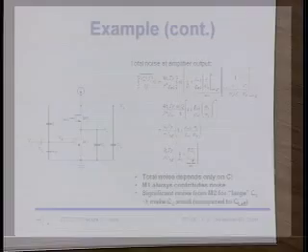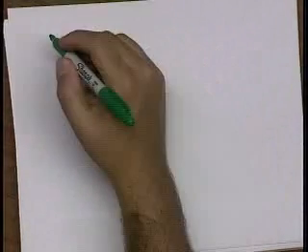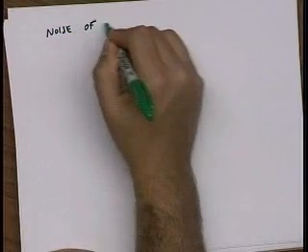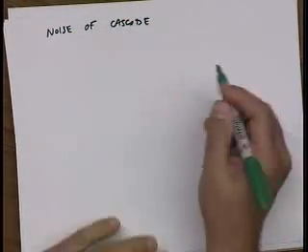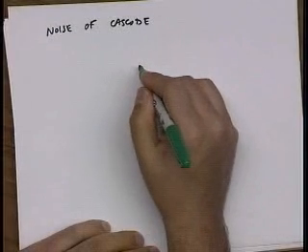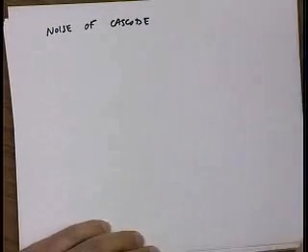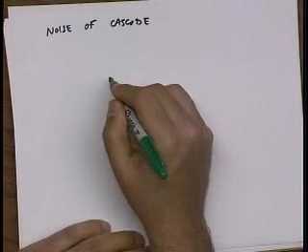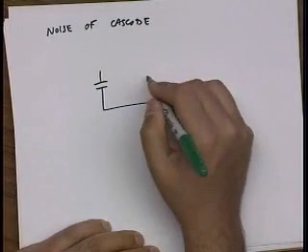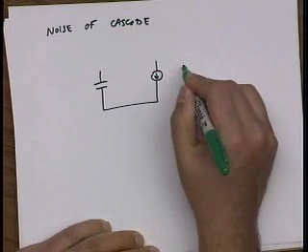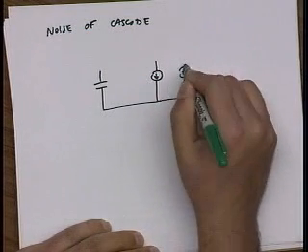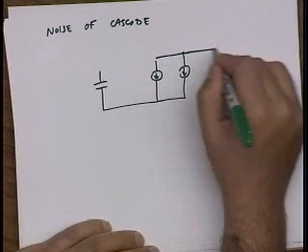Okay, just very quickly, since I didn't do the algebra on the noise, I wanted to show you guys who haven't seen this before why the cascode device does not contribute noise. And we're going to do a very simple calculation. So you can do all the algebra, but you won't get much intuition unless you play with the results, as we've seen in these slides. And then once you play with the results and you see that the cascode is not contributing much noise, you can do a simple calculation like this to find out what's going on.